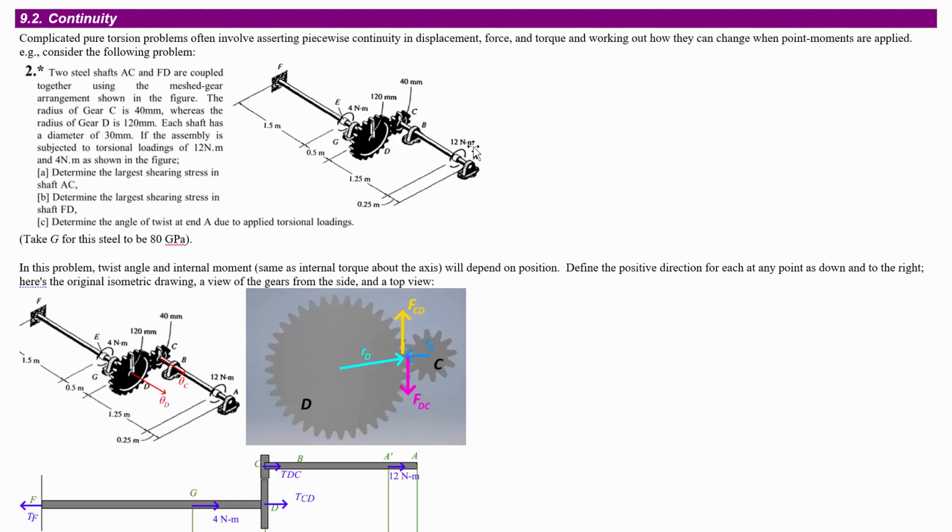So you see, this is building up the moment by jumping up to there, but how do you get that? How do you get energy for nothing? Well, you lose on the displacement. The twist angle that this one has is going to be a lot more than the twist angle that shows up here. So for this gear to be applying the same force to this gear as this gear is applying to this gear, we end up with a couple of different things happening.